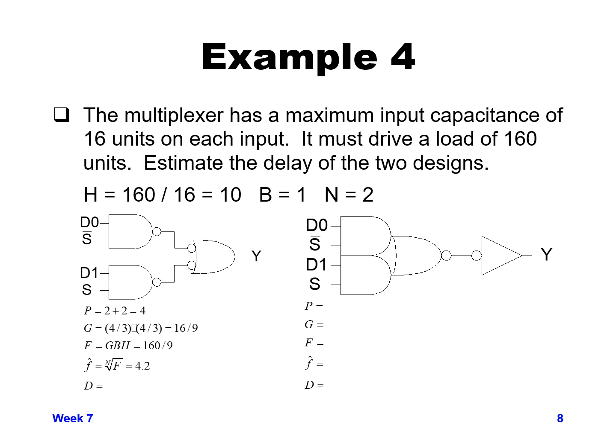And then finally we can calculate our path delay, which is capital N times the minimum stage effort F. So we have 2 stages that each have a minimum stage delay of 4.2. We multiply them, and then we have to add the path parasitic delay to that.